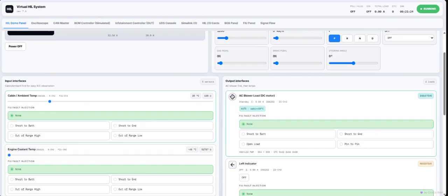Behind choosing this ambient temperature, there is some electrical characteristic that we will be studying, and this ratio of temperature in degrees to resistance in ohms, we have tried to replicate in the MATLAB Simulink environment. If I take you to the subsystem here, we have prepared a 1D lookup table to convert the value from degrees Celsius to resistance. But to implement this logic, we have to go through the electrical characteristic of that particular temperature sensor's part number.